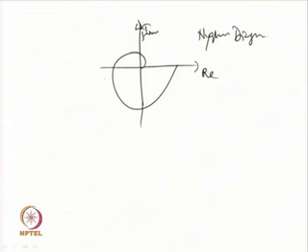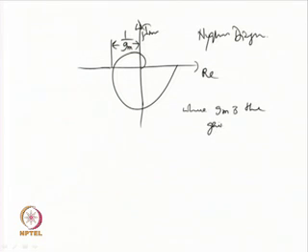When you have got a Nyquist plot of this form, then this gives you the inverse of the gain margin. Let the gain margin be GM, then this span will be 1 upon GM, where GM is the gain margin of the control loop. Okay. So, I will write two analytical expressions corresponding to this operating point, which is giving a gain margin of GM.